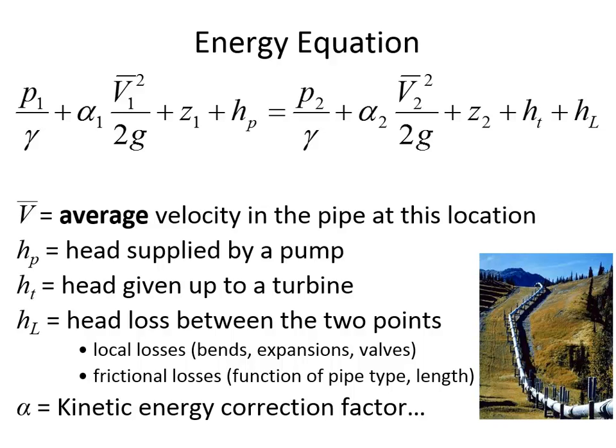If we had this situation, and we put in a couple elbow valves along the way, here we go. So here we'd have a local loss here and a local loss there, and maybe if we put in a valve here, there'd be a local loss there, and then also there would be frictional losses. So there can be both frictional and minor, local losses in the same system. Local and frictional can coexist, yeah.